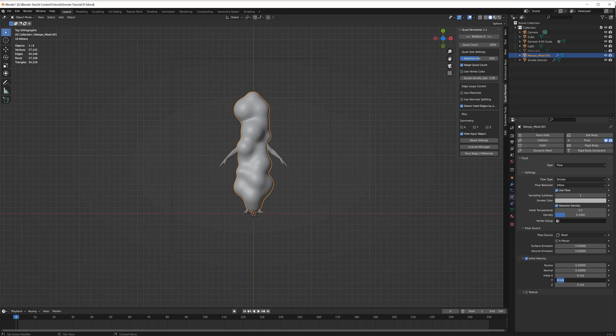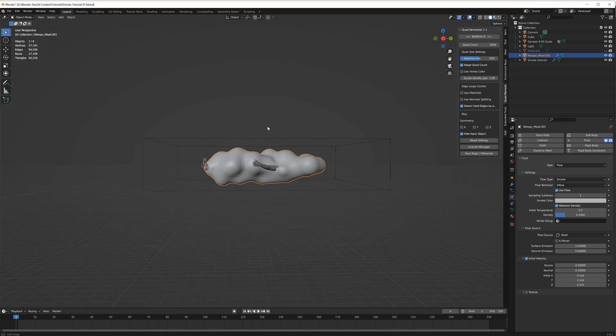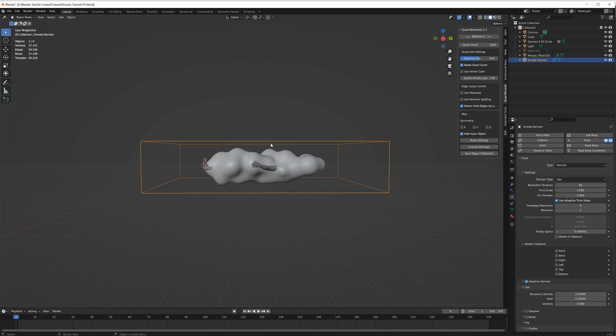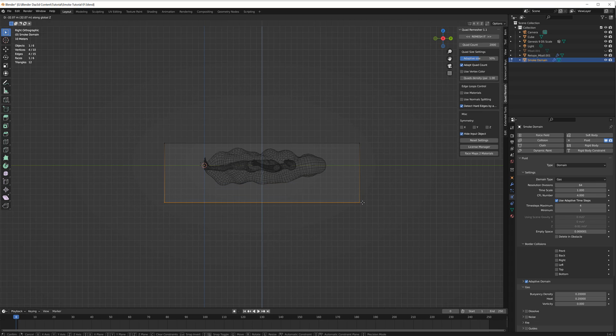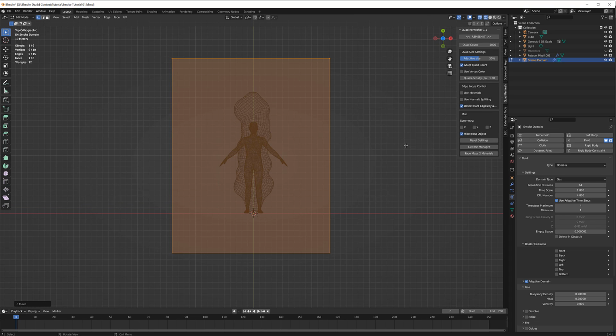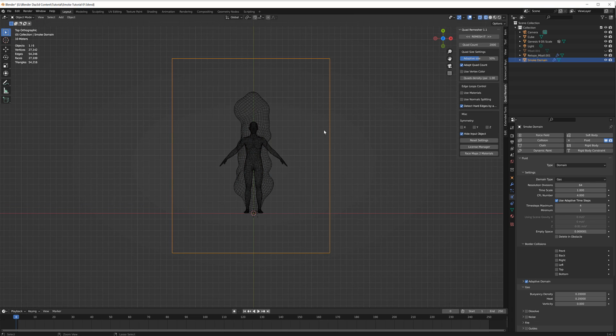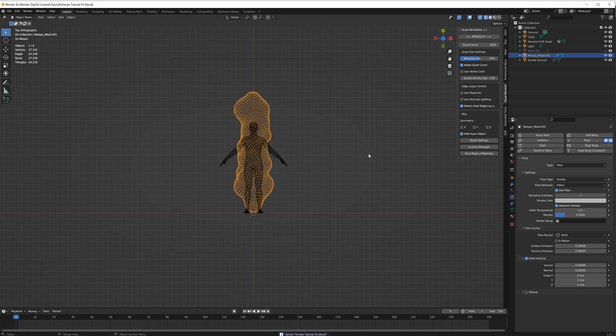And I'm going to set Y to 2 because the Y-axis is the one that I want to be as if it were vertical, not the one that's actually vertical according to the gravity of Blender, if that makes sense. Because of the way that we've rotated this onto its back. If I were to just leave it with the default settings, the smoke would move in a way that isn't what we want. There we go. And I've got that ready to go, I think, so I'm going to save.